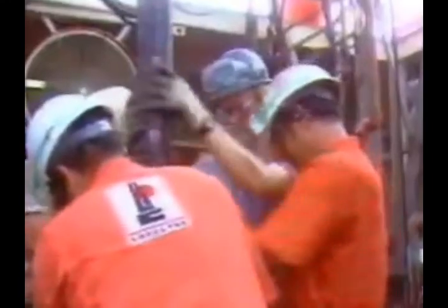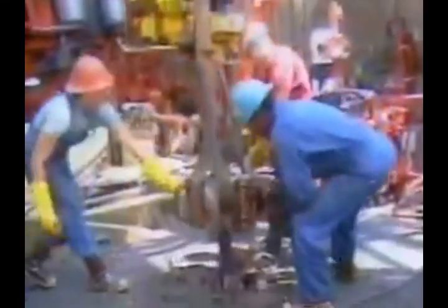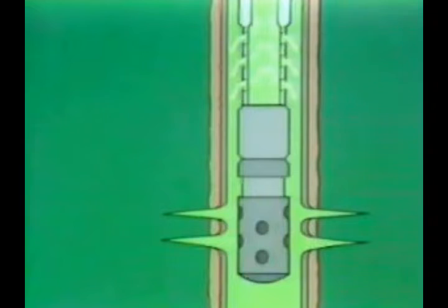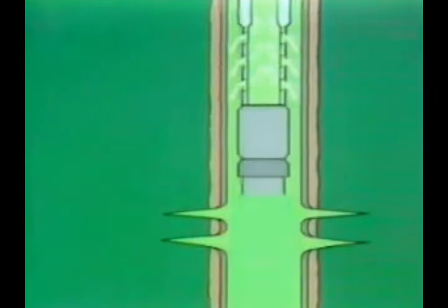With tubing conveyed perforating, a hollow carrier gun is run into the well on the tubing string. The tubing may be run dry or partially filled with a fluid cushion to establish the proper level of underbalance. The packer is set and a vent is open to equalize the pressure below the packer with the tubing. The gun is fired using mechanical, electrical, or pressure activation, and flow is immediately established through the vent. The gun may then be dropped into the rat hole for full-bore flow.